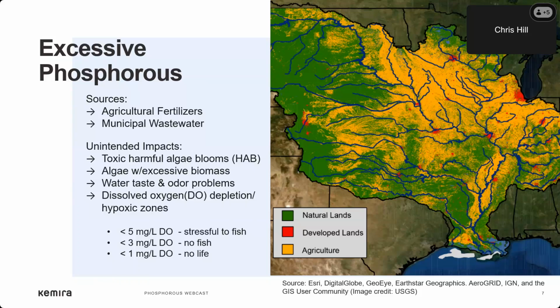So the process of eutrophication, where excess nutrients cause algae overgrowth, is followed by death and decay of algae by aerobic bacteria, leading to oxygen depletion in water bodies that receive discharges from municipal and industrial wastewater treatment plants. Eutrophication, because of oxygen depletion, causes harm to aquatic life and creates dead zones.